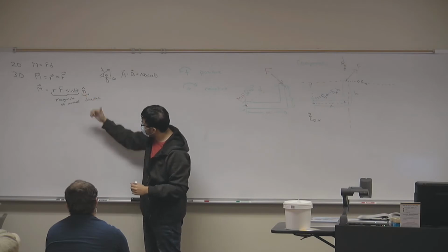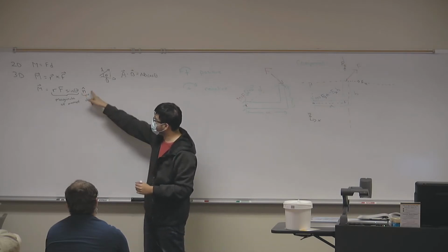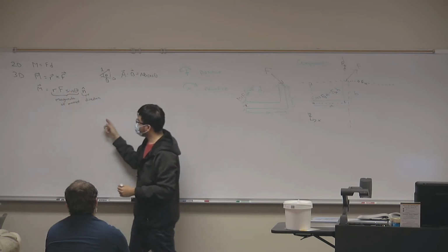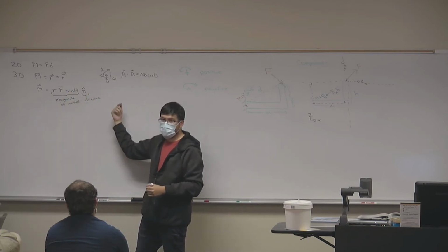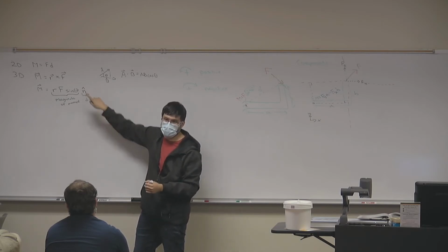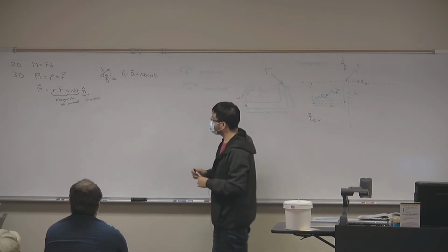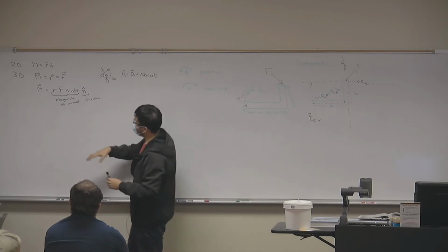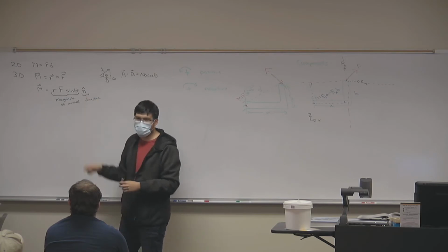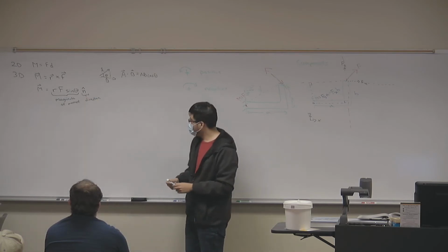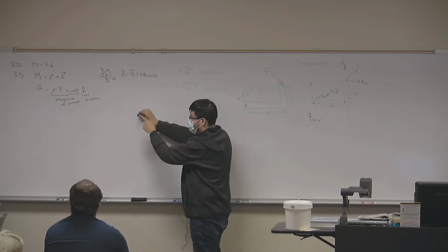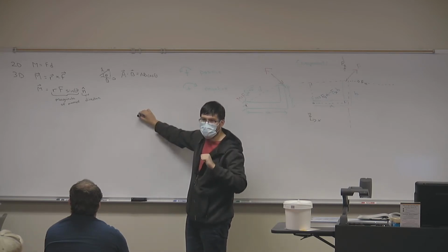if we look at the axis that passes through my unit vector n, this moment is positive if it rotates counterclockwise about this axis. So I'll explain myself. If I were to calculate the moment in 3-dimensional space, r cross F, I get this equation. And let's say that this n hat, this unit vector n, is here. That's my unit vector n. Just a small vector pointing directly forward.